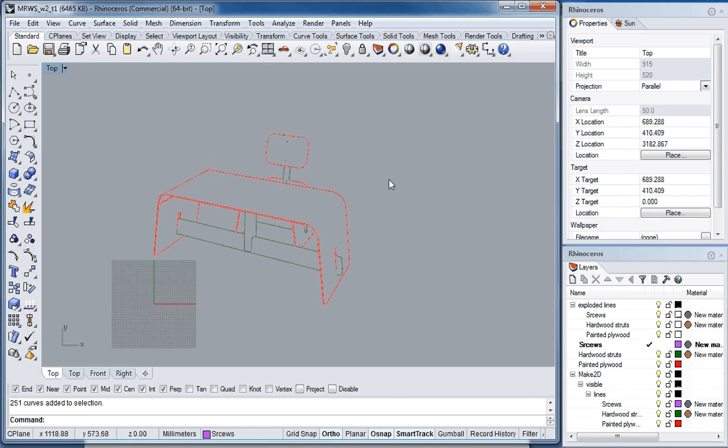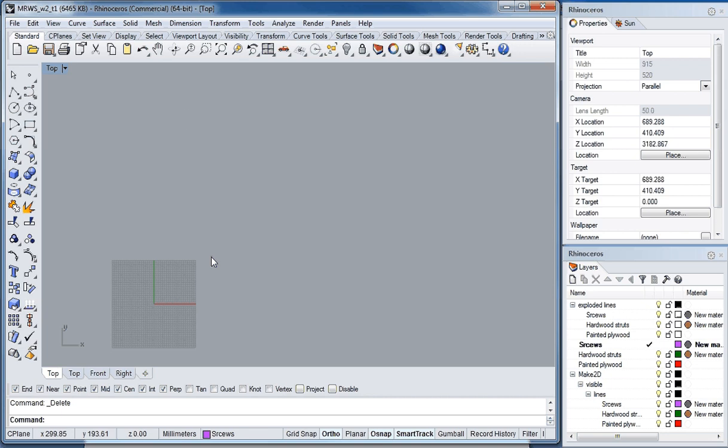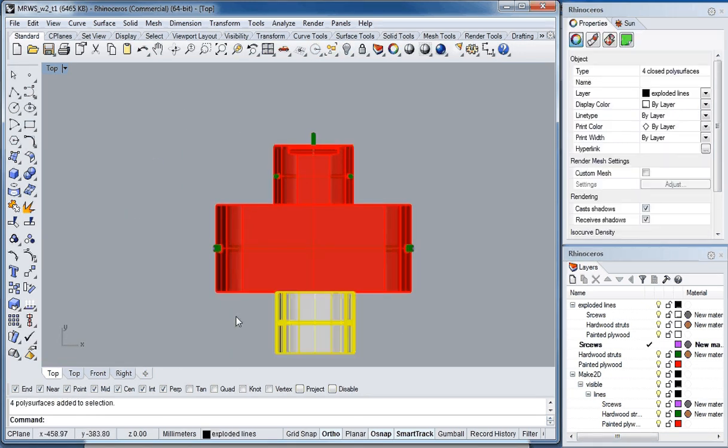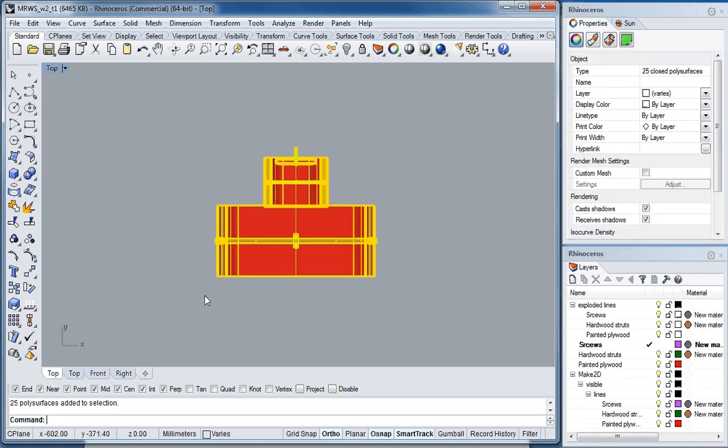So I'll just show you quickly now how to set a new C-plane. So we talked about construction planes last week. Basically, they're the imaginary piece of paper which your drawing is flush to. So oftentimes we'll need to create a new C-plane because the default C-plane is in the world view, but oftentimes your geometry might not be that way.